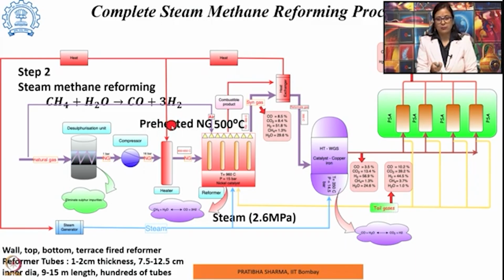The reaction takes place somewhere between 700 to 950 degrees centigrade. The reason for such a high temperature is that both your feedstock as well as the oxidant are inert, so a large amount of energy is required to make them active and react.